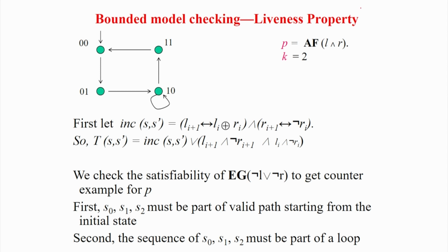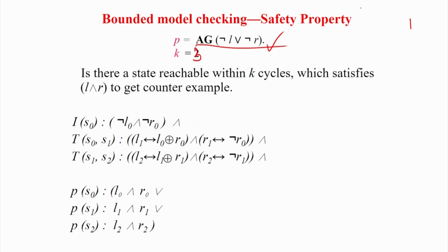Now we are going to see the liveness property. So what is the liveness property? One thing I should tell you is that this Boolean satisfiability check I have done manually, like putting 0, 1 and so forth. But in a general case, it will be a formula in CNF form, which I will discuss shortly, and then there are automatic solvers to do it. Exhaustive solving is an NP-complete problem, so there are heuristics. So do not go by this notion that I have done it manually. For large cases, there has to be automation.